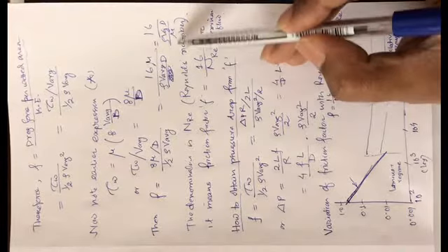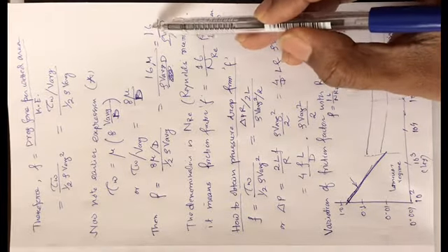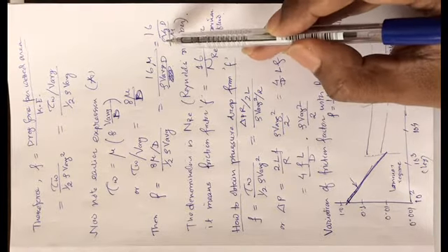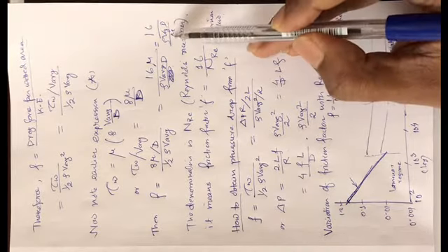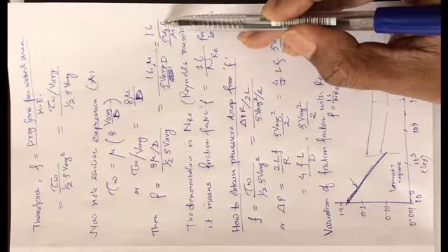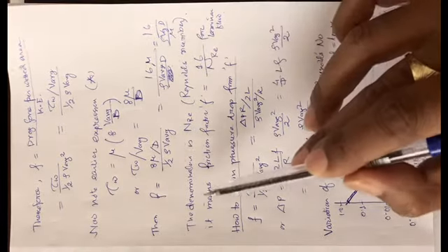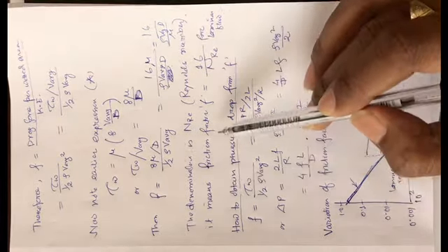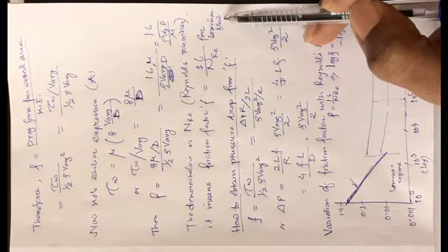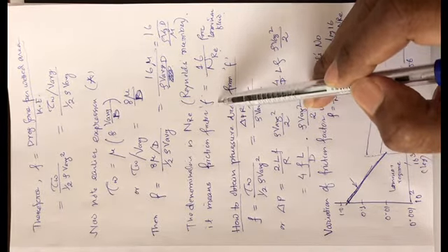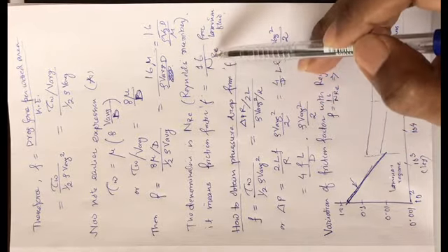Okay, this one. So now, if we know the definition of Reynolds number, what is there in the denominator? The denominator is rho into V average into d divided by mu. For a circular pipe, d means the pipe diameter. So rho V d by mu is called the Reynolds number. It means the friction factor is basically 16 by Reynolds number. Of course, it is for laminar flow. That is quite interesting information, and that was our idea actually. We wanted to know a factor named Fanning's friction factor, that is basically 16 by Reynolds number.